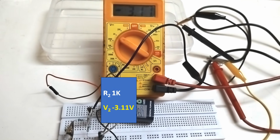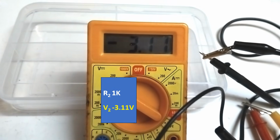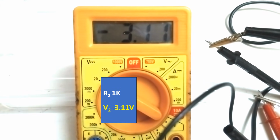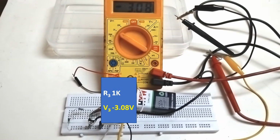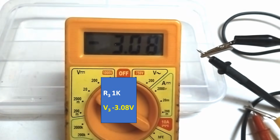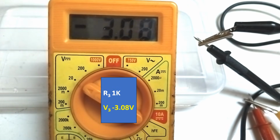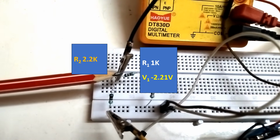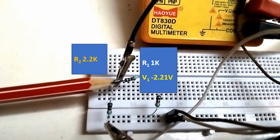This is the voltage drop across the second 1 kilo ohm resistor, minus 3.11 volts. You can see here in the multimeter. This is the voltage drop across the third 1 kilo ohm resistor. You can see that it is minus 3.08. So the sum will be almost equal to the 9 volt power supply. So adding the negative voltages or potential differences and the positive supply voltage, the algebraic sum will be 0.